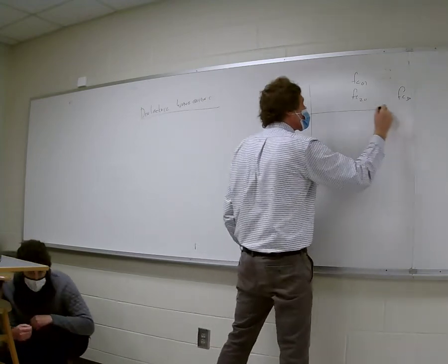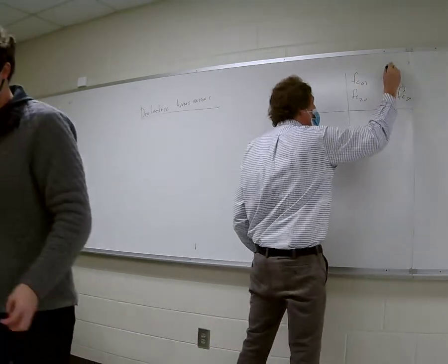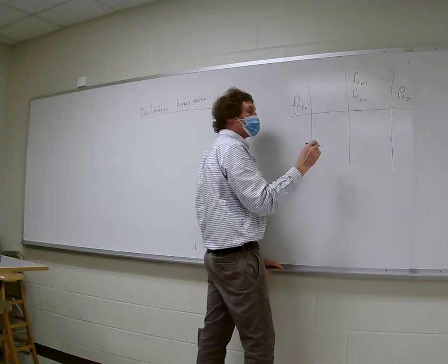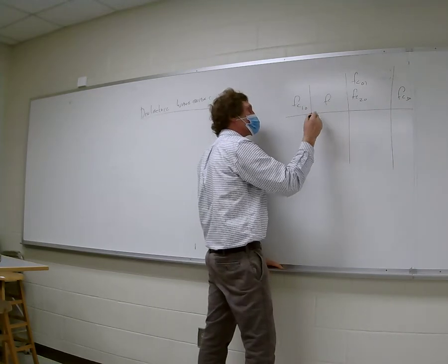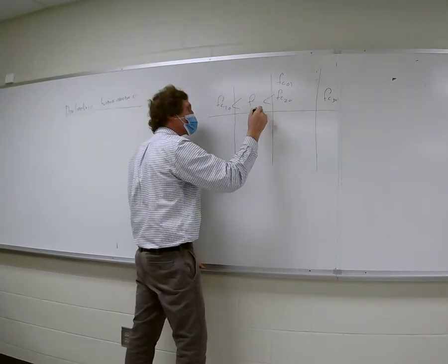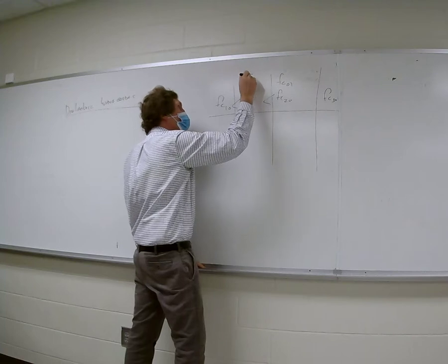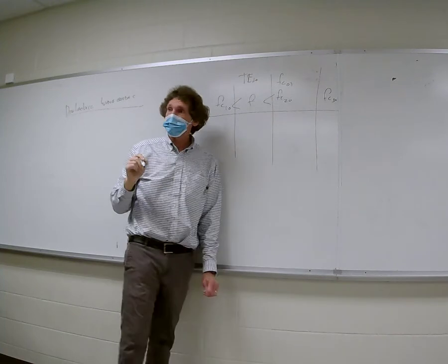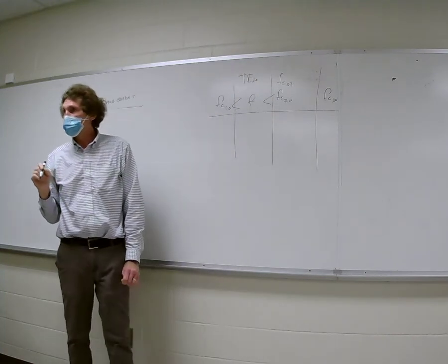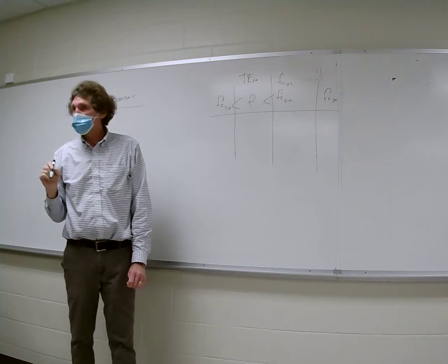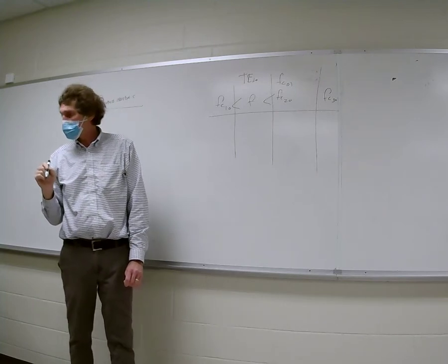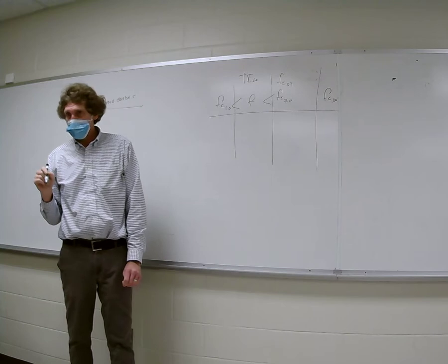When you have these, your frequency of operation, if it's greater than this and less than this, only the TE10 mode goes. That's the thing I wanted to stress. Okay, everyone? And that's the way that quiz is set up. That's the way rectangular waveguides 99.9% of the time work.